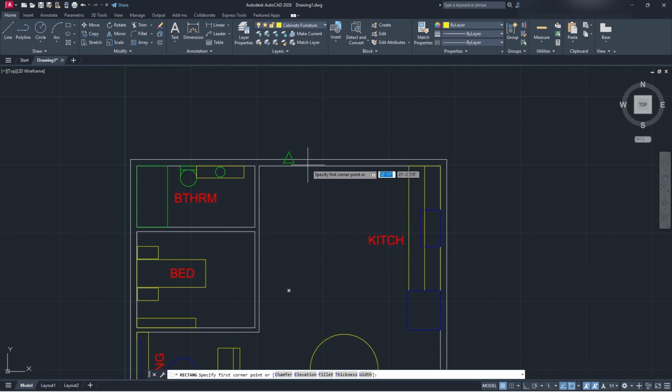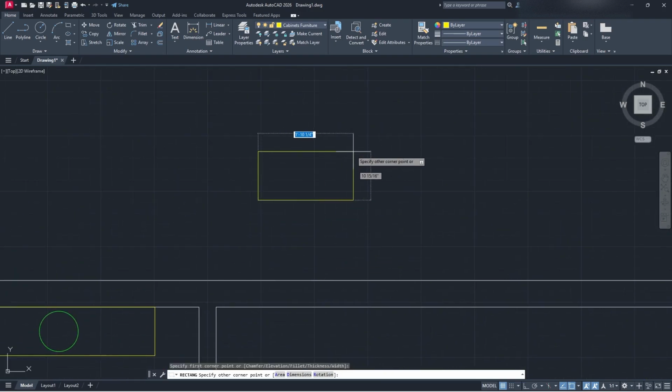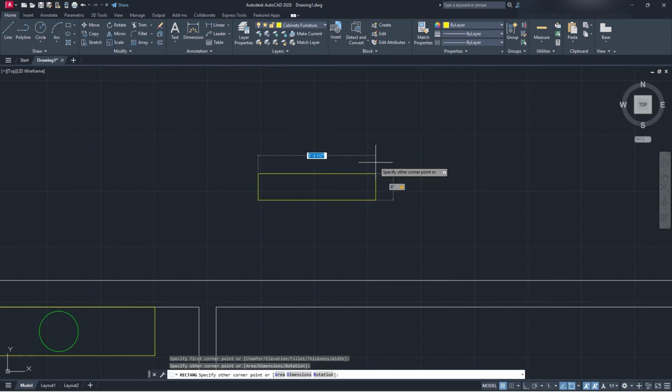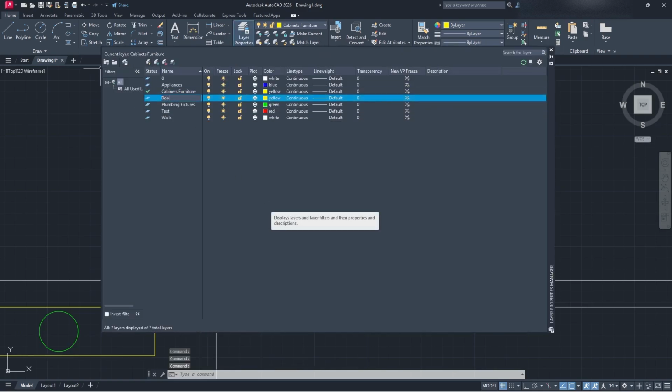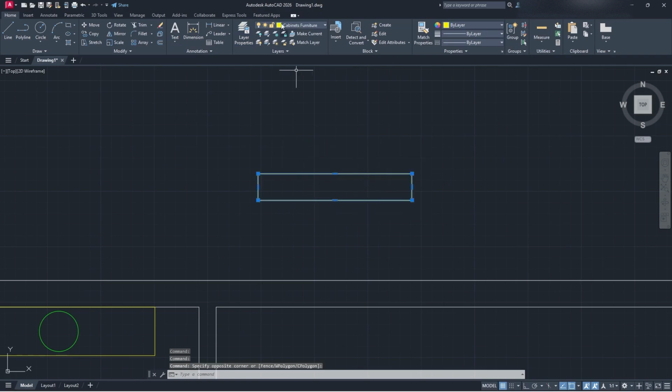So what we need to do is grab our trusty dusty rectangle, and we're going to come here and create our doorway. I'm going to make it 6 inches thick so that it fits with our wall, sorry. And then I'm also going to make it, let's say 32 or 36, well, let's do 36 inches in length there. I'm going to go here to my layers, create a new layer, and call that door. Then I'm going to make it a light blue or a cyan. I'm going to click that, get out, select this, switch it back to door, and then I have my door right there.